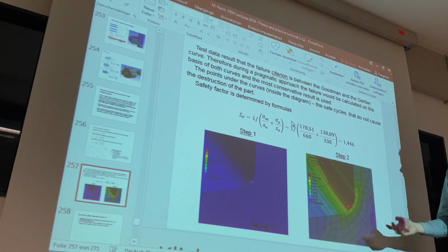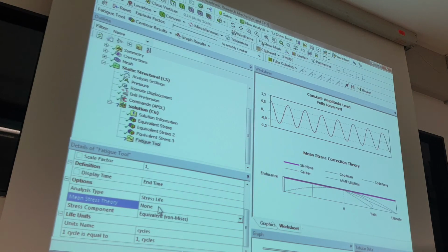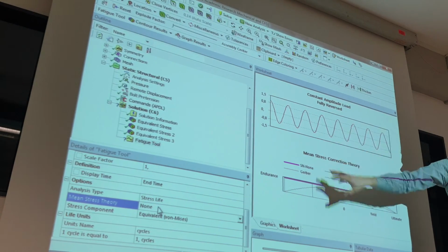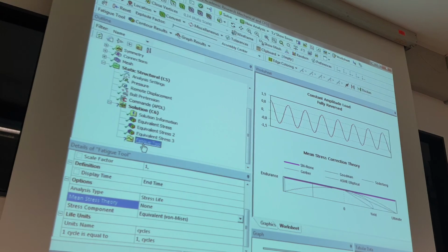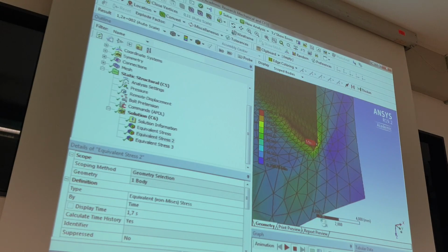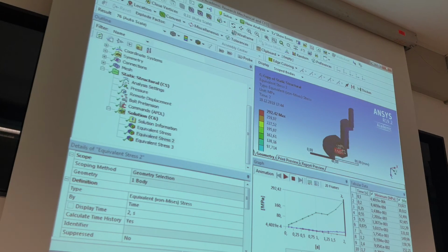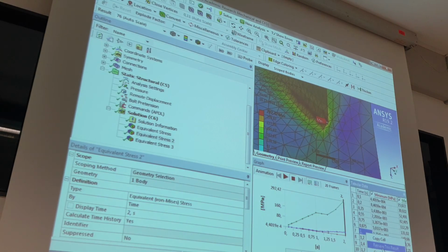And it's easy. We need only 2 points: the maximum stress. In ANSYS, with this tool you can show the safety factor at all points, but it doesn't work so easily, and normally it's not important. We need only the maximum place, only this point, with load and without load. We have these loads: 0 max, 0 max, 0 max. What we see is that at maximum load, time step 2, the stress is 229.